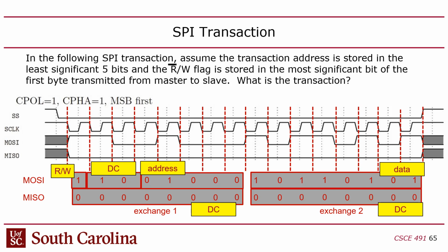But in the ESP32, there's SPI hardware, right? How many channels do you know? I am not sure, but at least 2, maybe 3. Maybe more than that. So when you use hardware SPI, you're limited to however many physical SPI interfaces are on your chip, and different chips have different numbers. I think even the Raspberry Pi has hardware SPI, right? One of them on the ESP is dedicated to the SPI flash, so you can't really use that one for anything else. But I think there are 2 others that you can actually use.